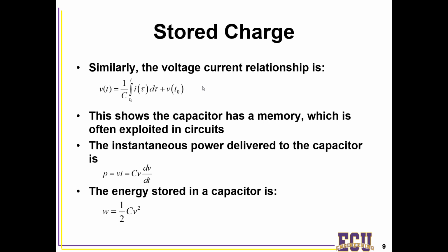And so you need to wait a certain amount of time just to make sure that charge is discharged before you start working, or you may find yourself shocked by this capacitor. A real capacitor actually has a parallel resistance. We'll talk about that in just a moment. So capacitors in the real world will eventually discharge if just left to their own devices, but an ideal capacitor will store that charge forever.